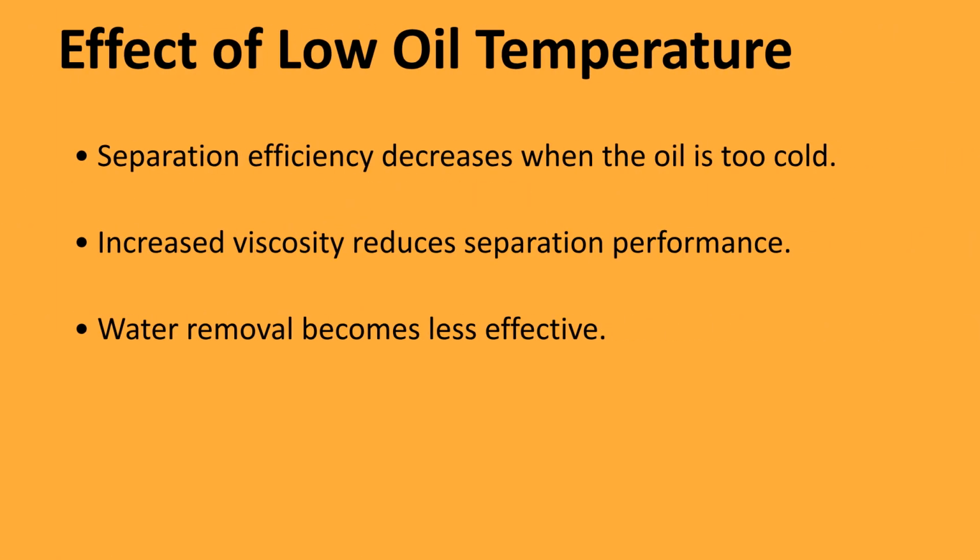If the oil temperature drops too low, separation efficiency will decrease significantly. This happens because increased viscosity hampers the separation process inside the unit. As a result, the unit becomes much less effective at removing water from the oil.